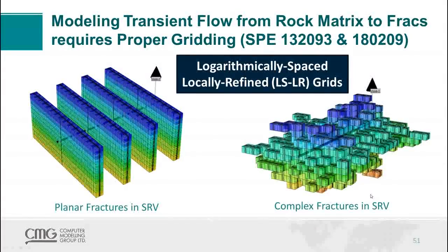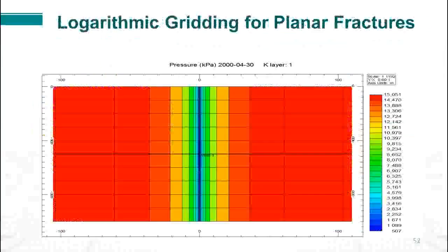And also, another very important aspect here that we like to deal with is the handling of both planar and complex fracturing and the application of our locally refined, logarithmically spaced grids to those scenarios so that we can model transient flow from the matrix to the fracture.